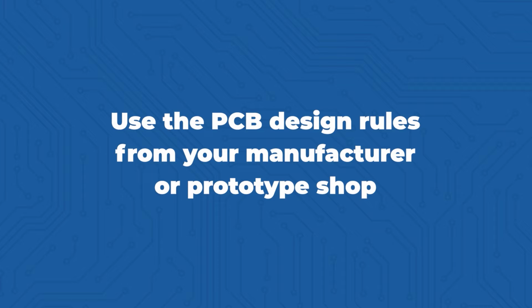You don't want to design your board assuming that you have a 5 mil minimum trace width, and a mil is just a thousandth of an inch. It's a common unit of measure when doing PCB design. You don't want to design your board to use 5 mil wide traces, but then the process you plan on prototyping requires 7 mils as the minimum. You would have to go through and redo your design, or find a different prototype shop, or pay extra and have a custom process done that can meet what you've designed to.